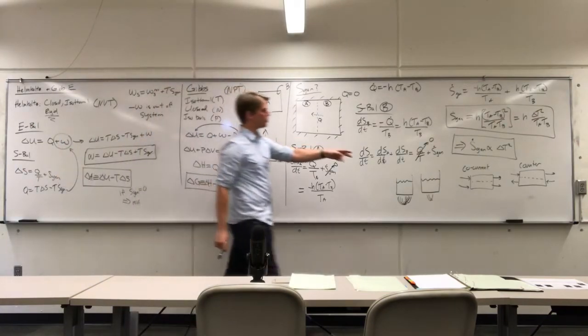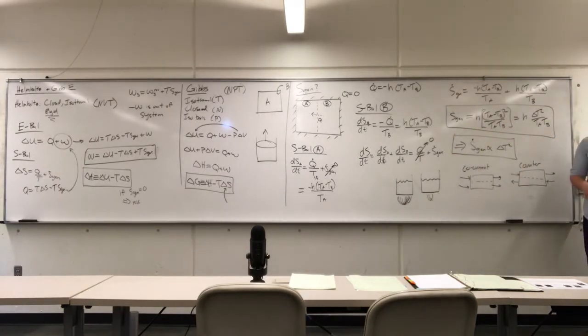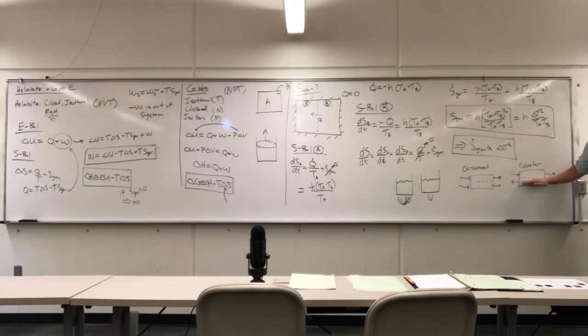So in the case of a heat exchanger, if I'm trying to design one, I maybe want a 50 degree C temperature gradient because I know that I can't have an infinitely long heat exchanger. But if I want to do this reversibly, my temperature gradient could only be maybe 0.001 degrees Celsius. That would result in a very large heat exchanger, which costs money for copper, for steel, for just space that it has to be occupied in. So that's the engineering decision that has to be made. How much energy do you want to throw away when you go about and do these things? Now, generally, people don't concern themselves about entropy too much when they're designing heat exchangers, but that's the principle that underlies all of this.